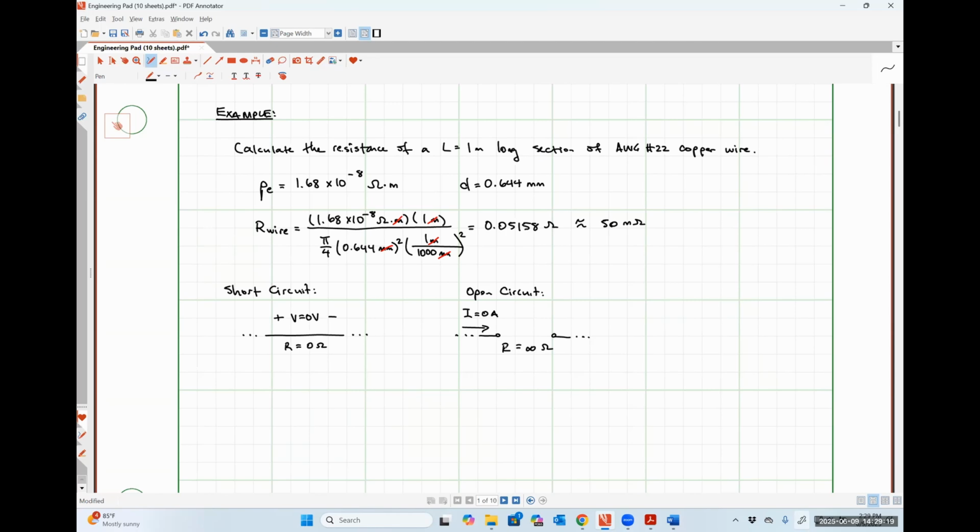This usually only works when either the gap between the conductors is very, very small, or conversely, the voltage is very, very large, on the order of thousands and thousands of volts. So whenever we see sparks from an outlet where we know that our outlet is only providing us 120 volts RMS, it must be because our conductors are just really close together, but not quite completing that circuit.